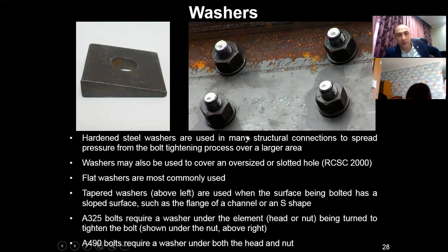Also, they are used to cover oversized or slotted holes. Sometimes holes, according to the class of the construction, can be made larger than the size of the bolt. In that case, washers are also very important.